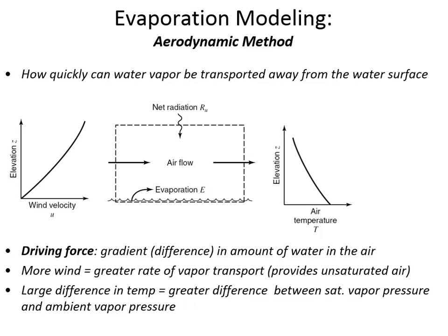And the same thing is true here. If you have wind flowing through that control volume, the wind at the bottom of the surface has no velocity. And so the moisture that's in the air is going to be transported away from the surface by diffusion, because it can't be advection. The velocity of the air is zero down at the surface.